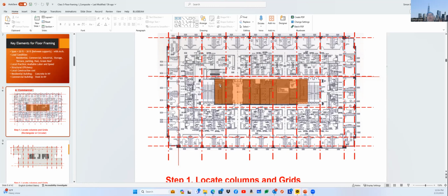Structural engineers, architects, and constructors in the market prefer to use a concrete shear wall as a backbone, so that this wall works as a load carrying element to support your floor load. So it's part of your wall taking care of gravity load, and also part of the lateral system to provide resistance against wind and seismic load.